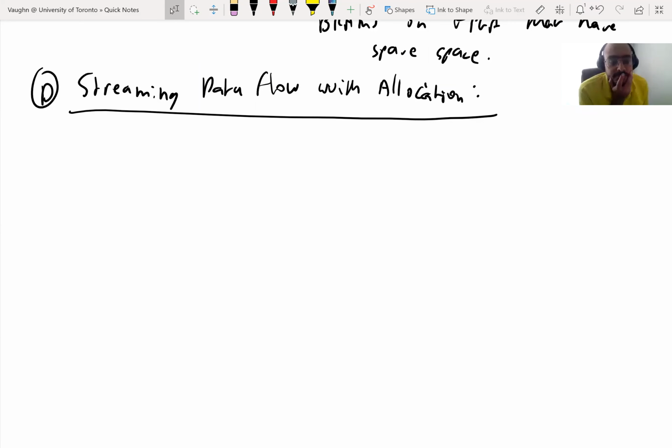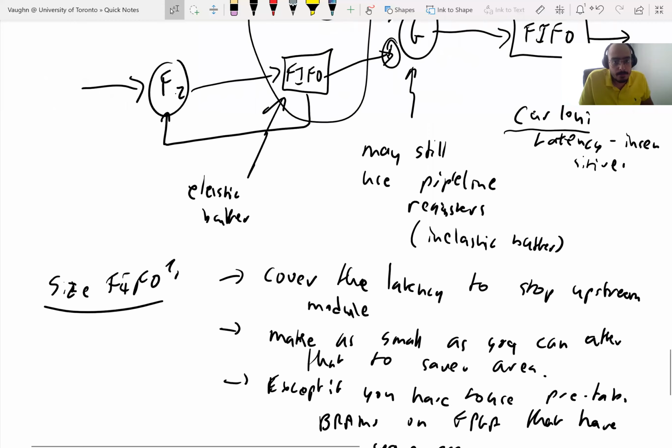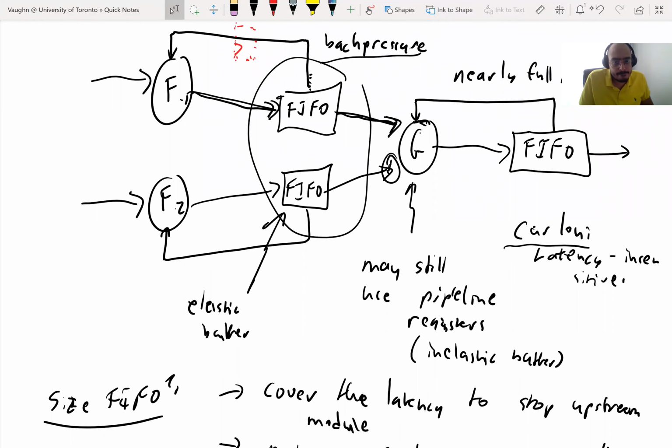So that's often done as a clock enable on all the registers inside of, let me say F. So say F1's pretty big. Maybe inside of it there are 5,000 registers and lots of lookup tables and multipliers and so on. The back pressure signal arrives. We need to stop F1, so it can't produce any more output. It can't corrupt its internal state. It's also not okay for it to start doing half computations. When it starts again, it's got to produce the right value.